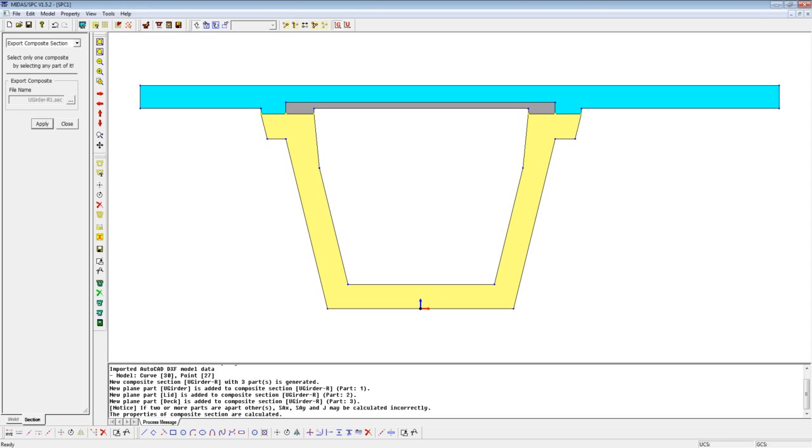Great. Another question that is coming in. So can we use rigid links instead of dummy elements? Rigid links shouldn't be used because they are infinitely stiff, and what they really do is they transfer entire load from one source to another, which is not the true behavior of the deck, because at any given time the force is being transferred with the member whose thickness is this much only. So the section stiffness is